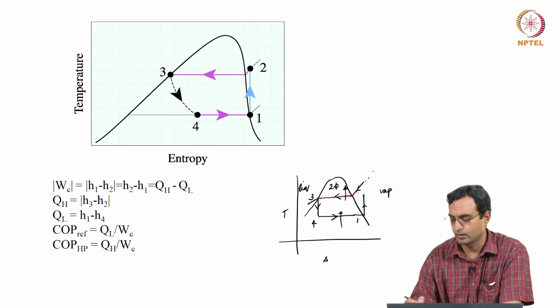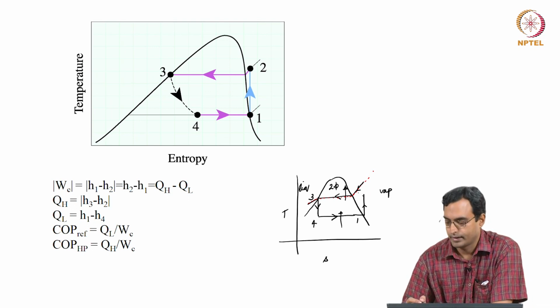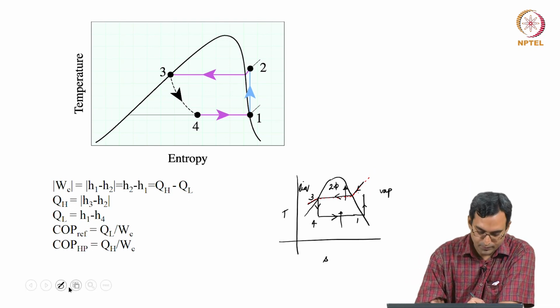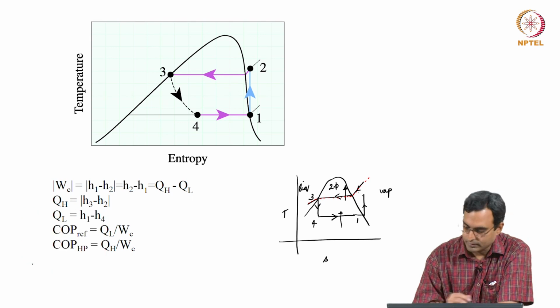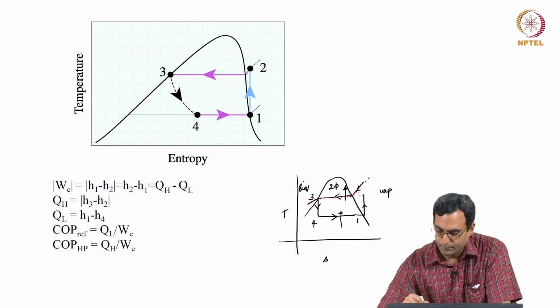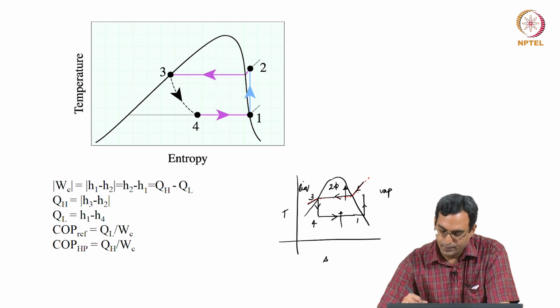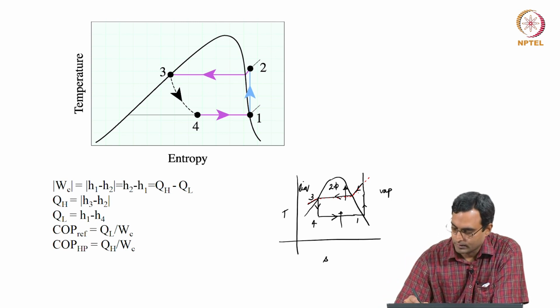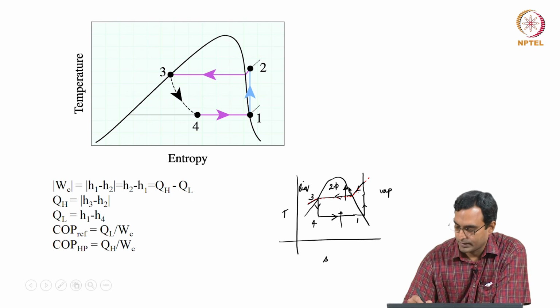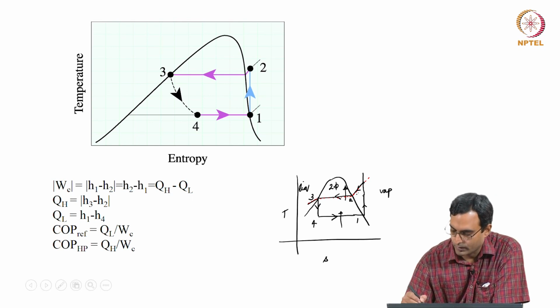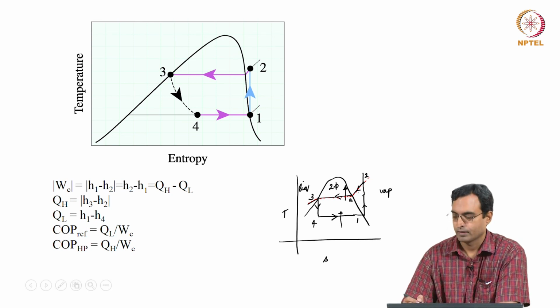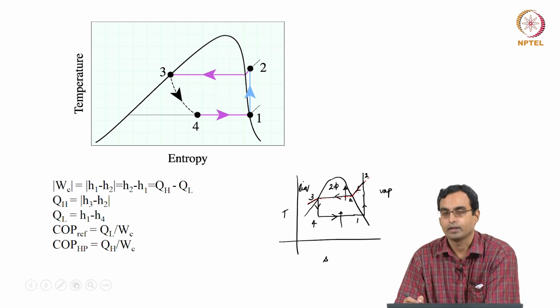That is what an isobar looks like on the TS diagram. So what we are trying to do is make use of that isobar. So instead of compressing to the pressure at this point, we compress to the pressure at 3. So if the isobar at 3 over here passes through this point, so what we see is this 3, and let me call this point A, and this point is 2. So the pressure at 3, A and 2 is the same.